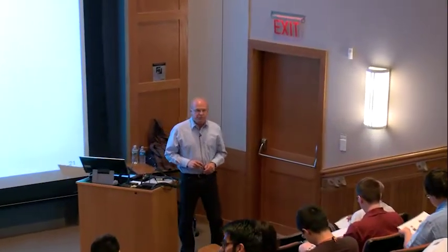Let me start to repeat something about what we have discussed as a last point, which was laser Doppler velocimetry, just to remind you what this technique actually was built on, and to see then subsequently the differences to particle image velocimetry. So first of all, this is a particle-based method where we have to seed suitable seeding particles into the flow.